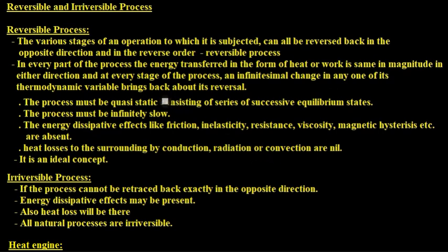So these are the four conditions that must be satisfied by a process to be reversible. The process must be quasi-static, consisting of a series of successive equilibrium states. The process must be infinitely slow. The energy dissipative effects like friction, viscosity, inelasticity, resistance, magnetic hysteresis, etc. are absent. And also the heat losses to the surroundings by conduction, convection and radiation are to be absent.